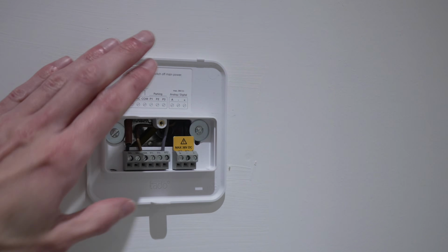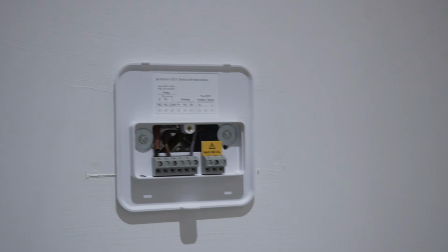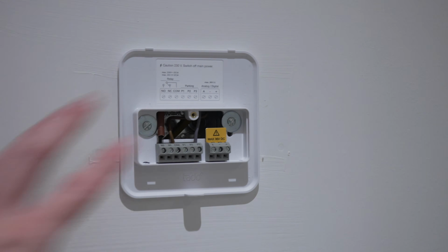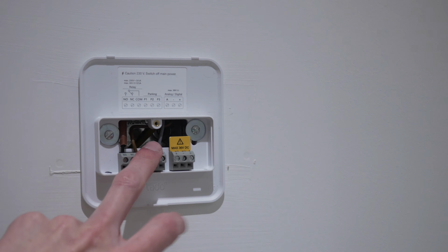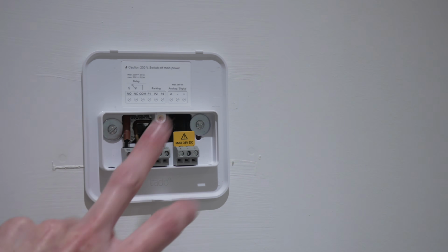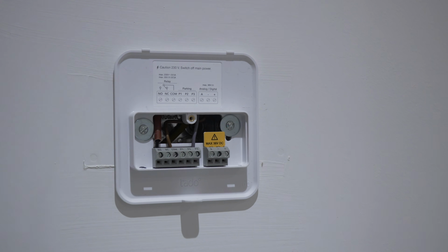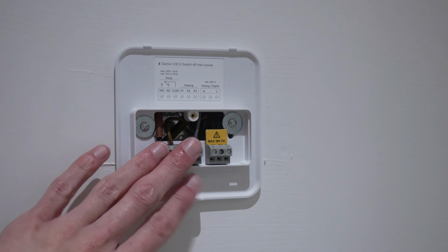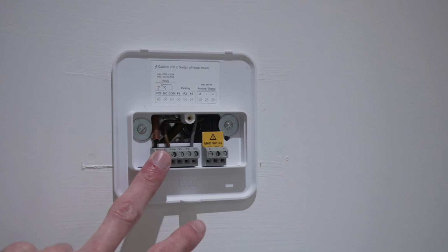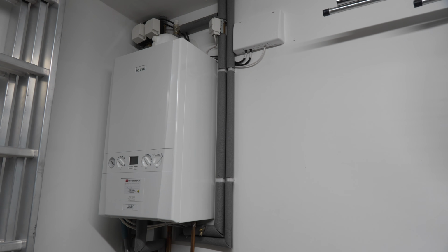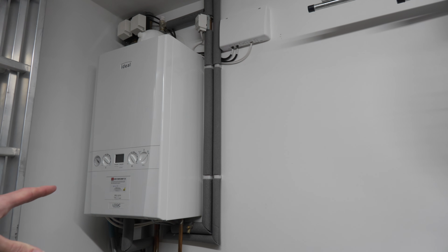However, of course, this thermostat is downstairs and then the other thermostat is in a completely different part of the house. So I can't just replace one of these with a Wiser hub because I don't have the switch wires for both zones at a single thermostat location. So instead, we need to find the wiring centre that these both wire back to and connect the Wiser hub into that instead. So that now brings me to the garage, which is where we find the boiler.